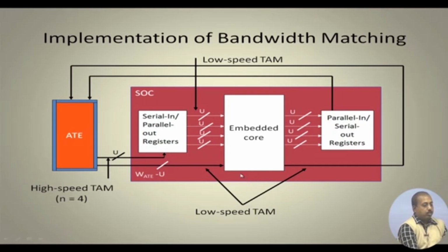That is fed here, there is a low speed TAM part, and that is being fed to the core. Then these U lines will again be converted via a parallel in serial out register into a serial value, and that will be transferred back to the ATE.